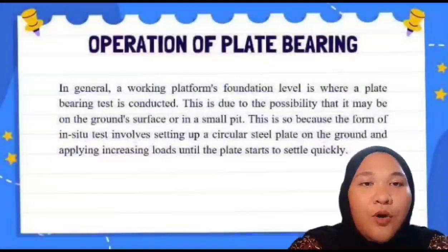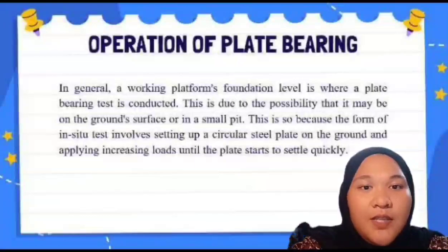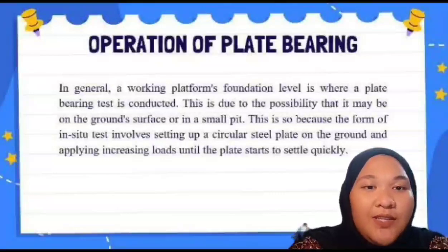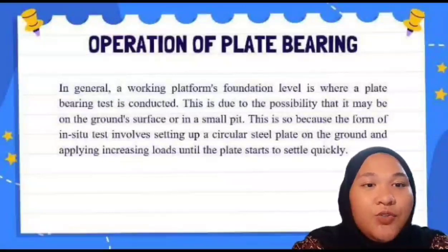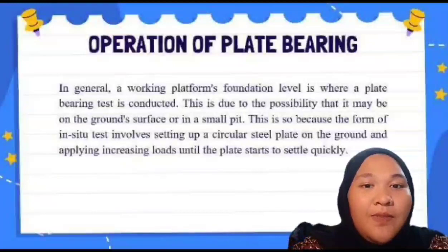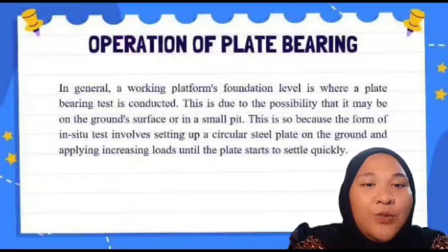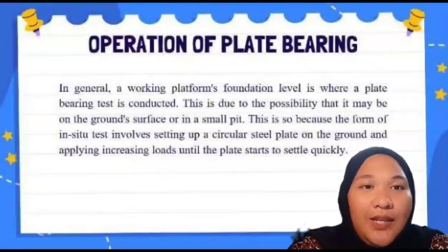Now we move to the operation of plate bearing test. In general, a working platform's foundation level is where a plate bearing test is conducted. This is due to the possibility that it may be on the ground surface or in a small pit. This is so because this form of in situ test involves setting up a circular steel plate on the ground and applying increasing loads until the plate starts to settle quickly.